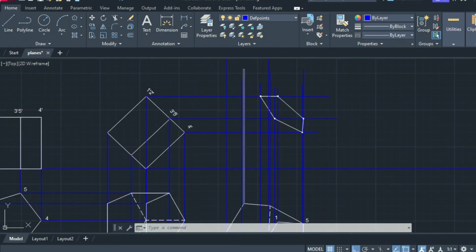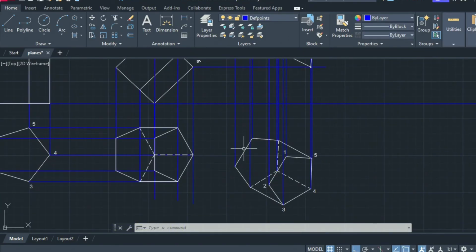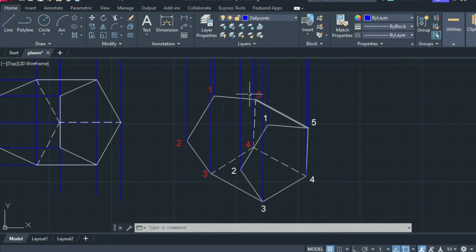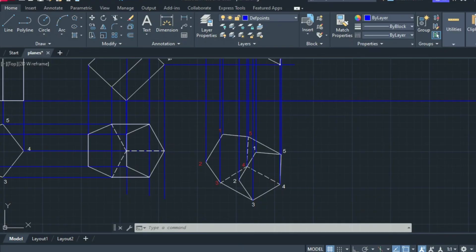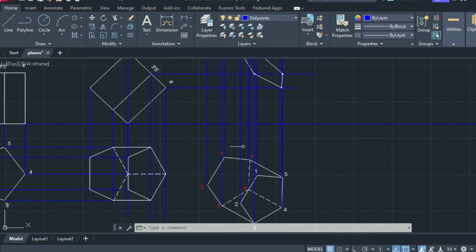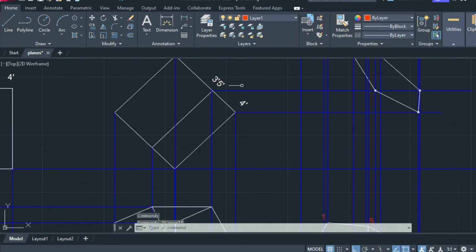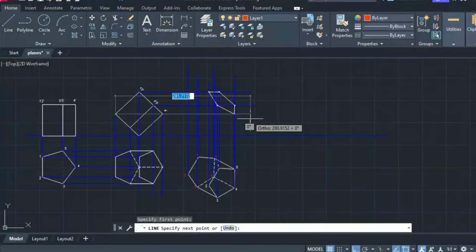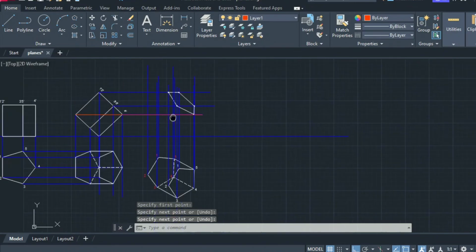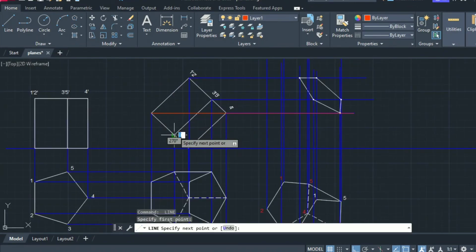Now similar points on this second base can also be observed. I just recognize these points which are on this second base. Now I have taken the projection of all these points vertically in the front view. Similarly, from the second base you can draw the projection lines. So I'll draw another projection layer for this second base.